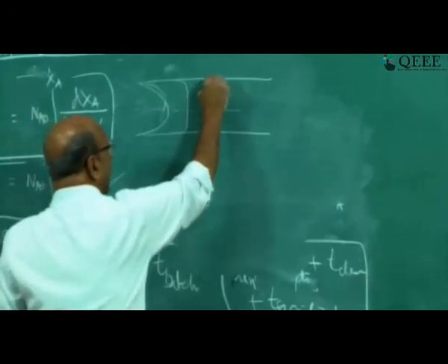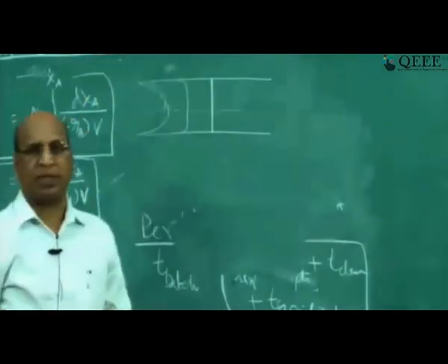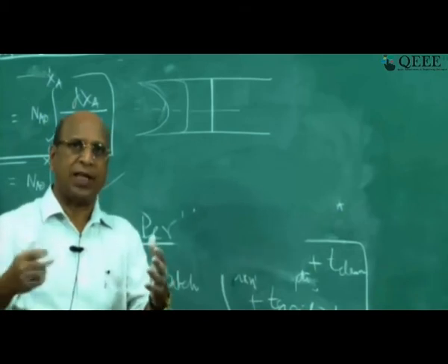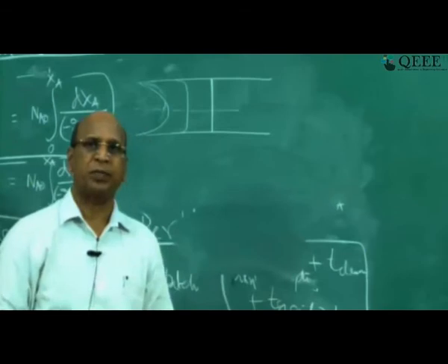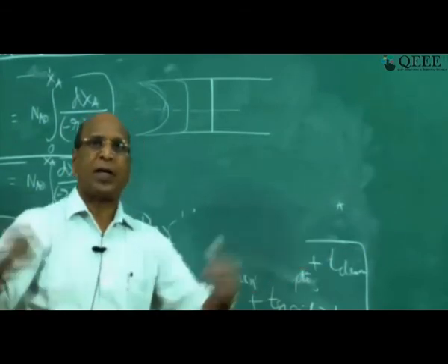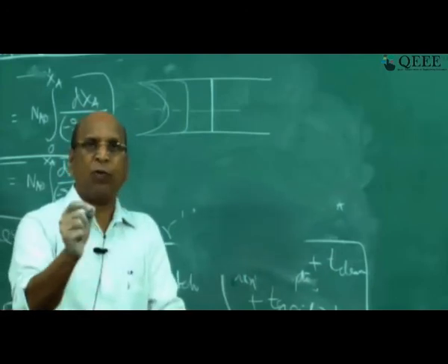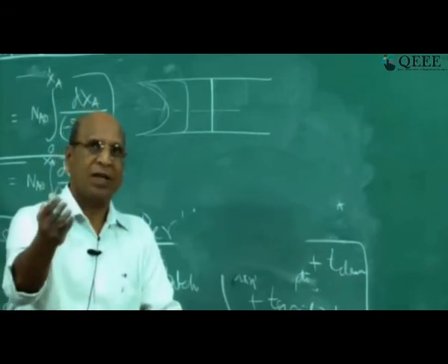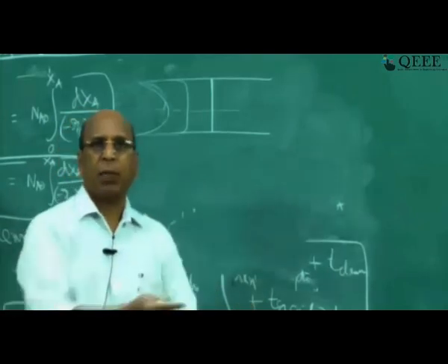To get a flat profile, you need almost infinite Reynolds numbers. When you have very high velocity, the residence time inside the plug flow reactor is very small. That is why you have to put in 5 kilometers, 10 kilometers of length. And when the reaction goes on within seconds, as in gas phase reactions, it is very easy to provide this time in plug flow reactors.